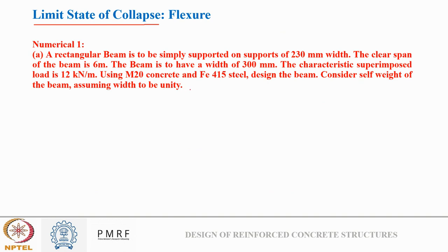This is a little more complicated question than what you saw in the NPTEL discussion of week 2. Try to solve this question, else I will tell you the solution. Here, the superimposed load is given. You need to calculate the self weight also. When you have the total load, since it is a simply supported beam, you can calculate the moment that it needs to resist, and you will use that to design the beam. So I have given you the initial hint. Try to solve the question. I will give you a couple of minutes, and then I will solve.